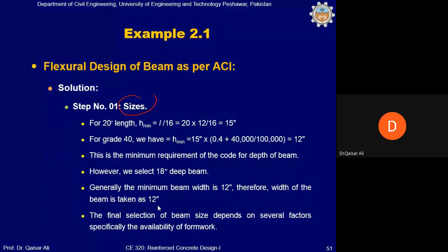And when reinforcement is placed in that small space, the concrete flow will be disturbed, and concrete will not flow easily around each and every bar. So the bond between steel and concrete will be weak. If you remember, last time I told you that we have to make sure the steel perfectly bonds with concrete, because it's one of the main requirements. If steel does not make a perfect bond with concrete, then the flexure capacity will not be what has been calculated from our calculations.